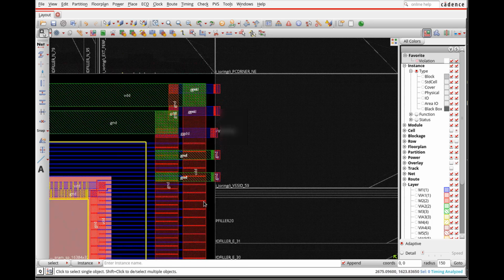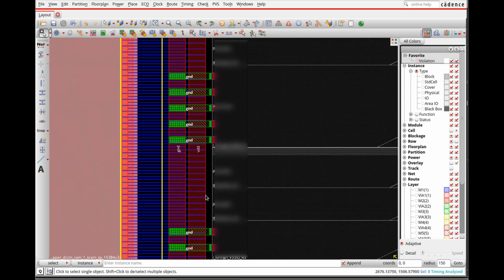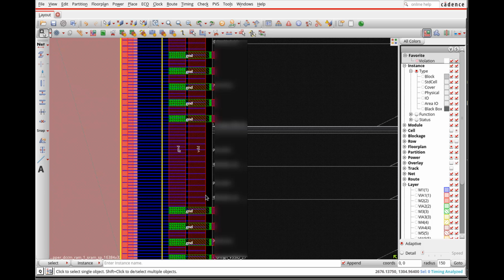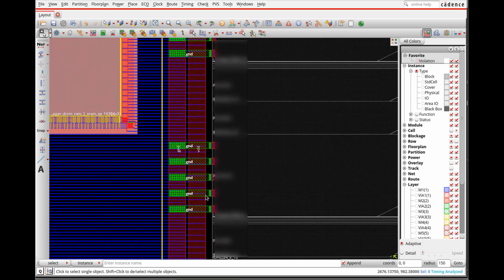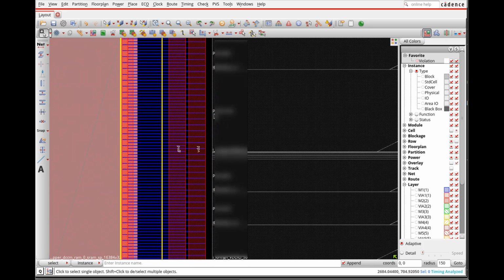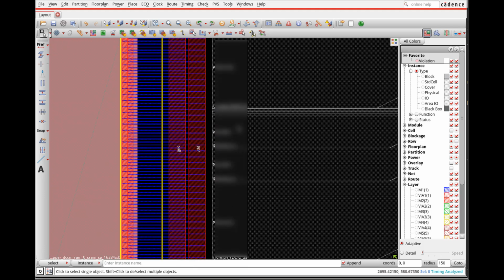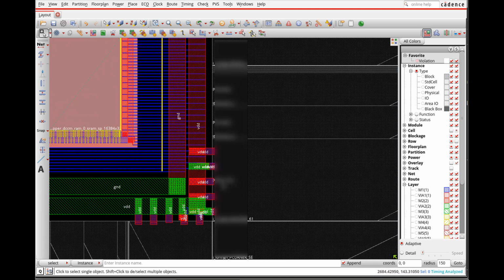And so these are the types of things that we're going to try to do. We can go down and see what these are also VSSs, right? All of these are VSSs that are connected, and that is what I kind of wanted to do. Okay. The VDDs don't have any pins on them, this type of VDD, so it didn't need to connect anything to the rings over there. So this one does have pins on it, so you see that it connected the VDDs to this ring over here, and this one as well connected the VDDs to the ring.